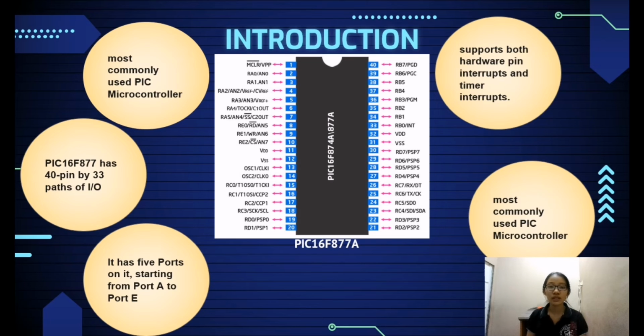The 40 pins make it easier to use. The peripherals as a function are spread over the pins. The PIC microcontroller consists of both hardware and software interrupts. If the interrupts are generated by external hardware, at a certain pin of the microcontroller, or an inbuilt device like a timer, they are called hardware interrupts. The software interrupts are generated by a part of the program, also known as external and internal interrupts.